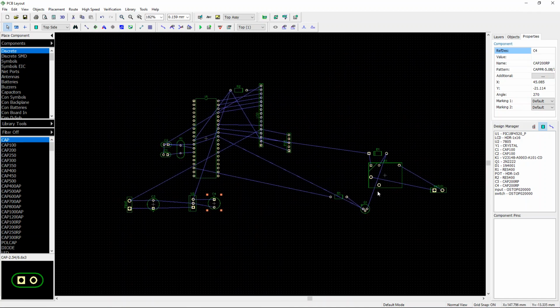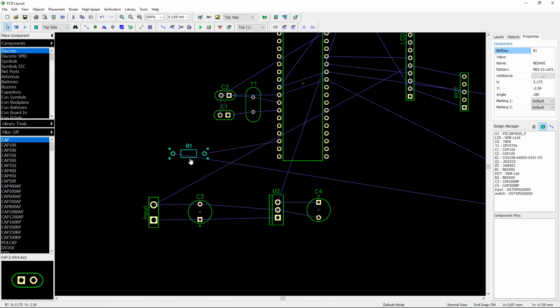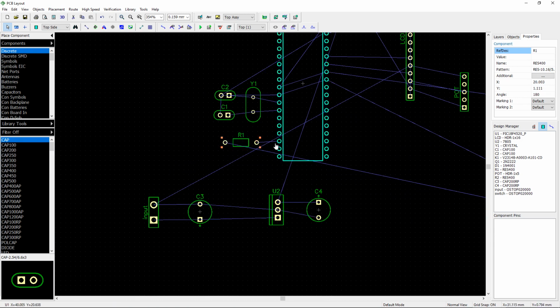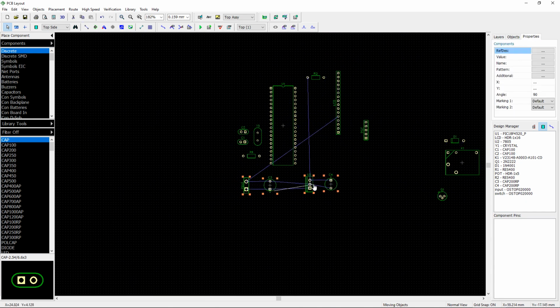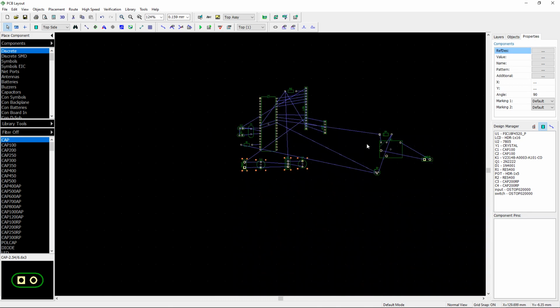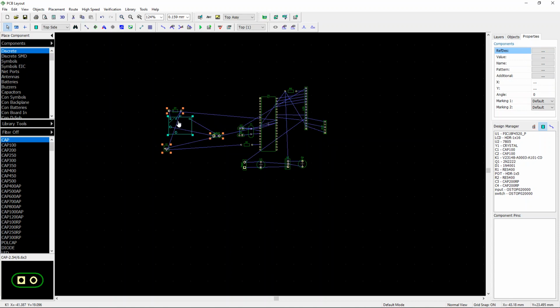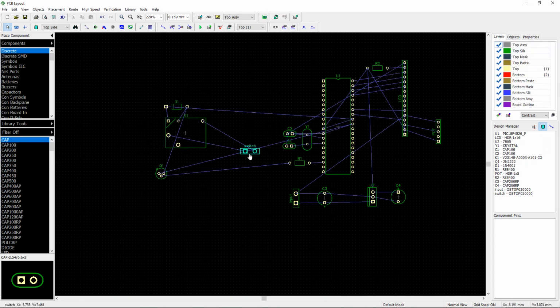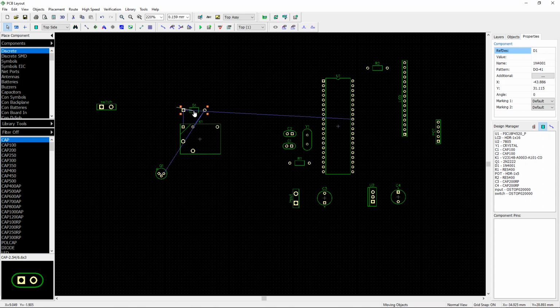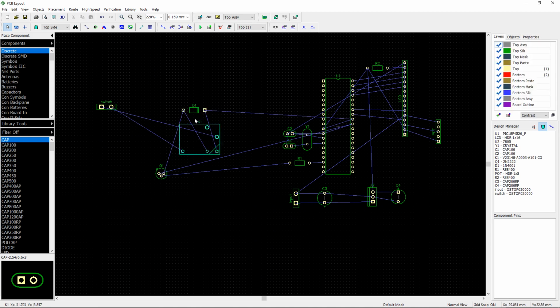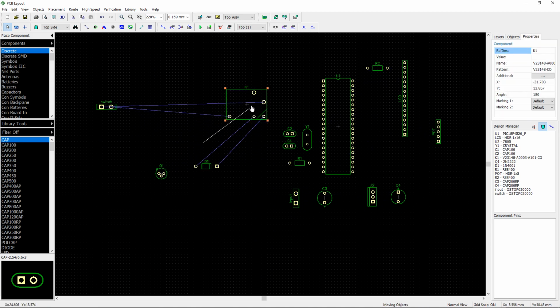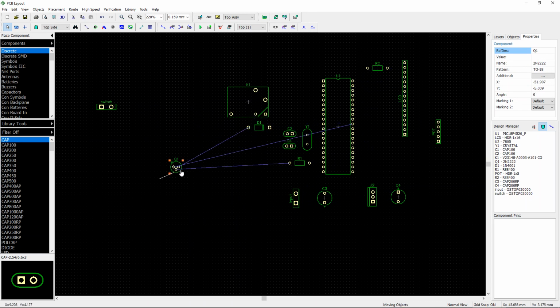Okay, next thing, let me put my relay there. I rotate this resistor so that pins connected to each other are closer, adjacent to each other. Then I move this so that we have a very small PCB. Then these components must come here. Okay, then let me just rotate this. Okay, right there. Yeah, actually move this over to there. Then the switch can be right here.